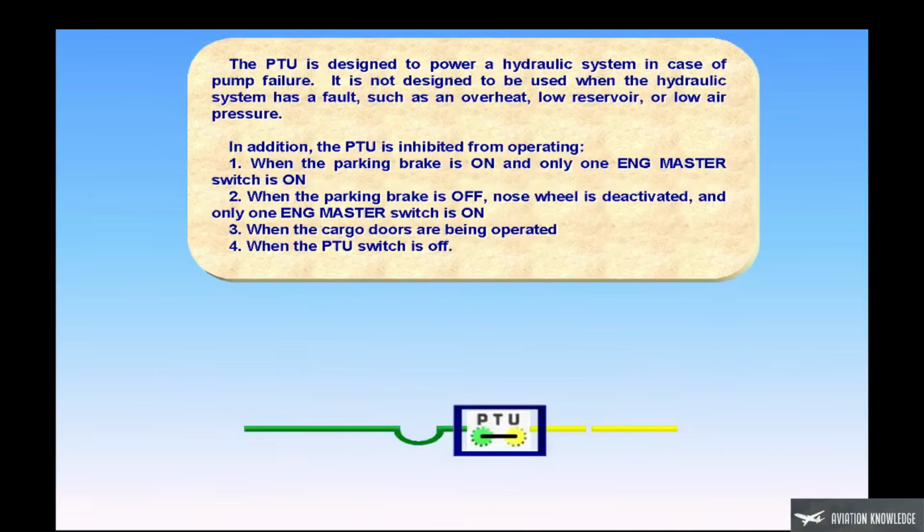The PTU is designed to power a hydraulic system in case of pump failure. It is not designed to be used when the hydraulic system has a fault, such as an overheat, low reservoir, or low air pressure. In addition, the PTU is inhibited from operating: